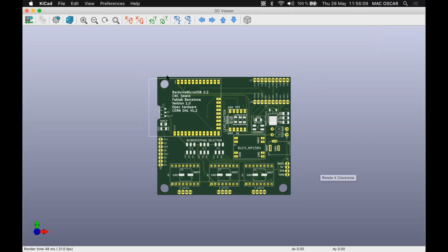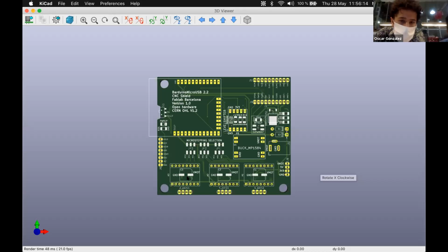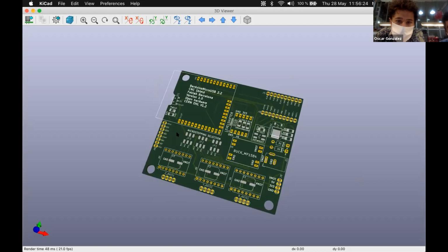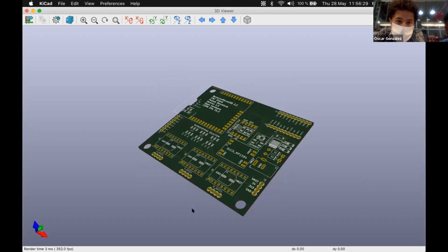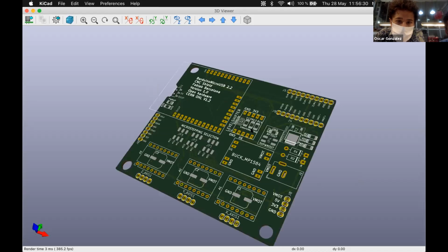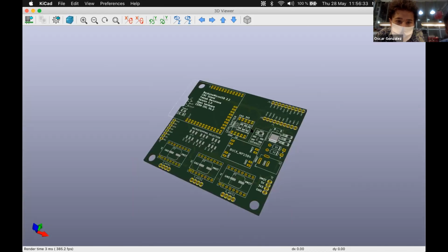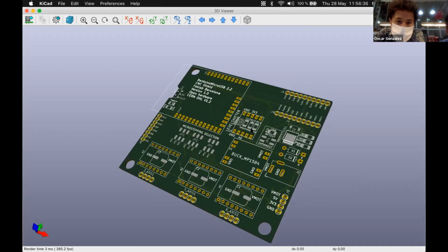Okay, but they can only be used for those functions, or is there any other option? You can use them for other functions because it's the same. These functions will be the same custom G-code commands. For example, right now, start will be with a G4, which is a pause or dwell command. But if you send the command whenever you want, instead of pausing, you can enable whatever thing. Let's say a servo, or I don't know.